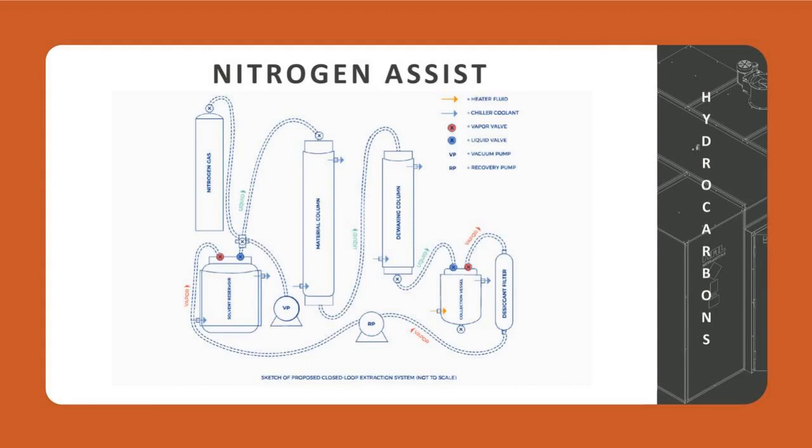So it effectively will push your solvent and your cannabinoid extracts through your closed loop system, allowing you to recover that solvent and allowing you to finish your runs a lot quicker. And so a combination of nitrogen and active solvent recovery goes a long way as far for improving your process times. Now we're down to like 30 minutes, let's say, depending on the size of your system.